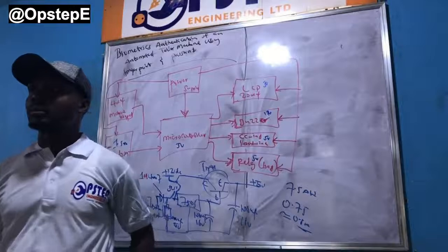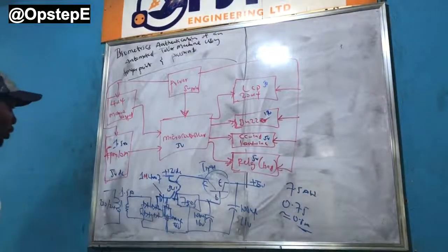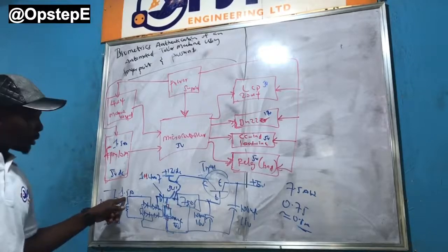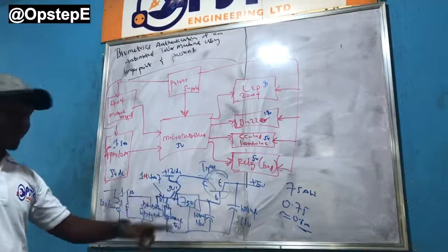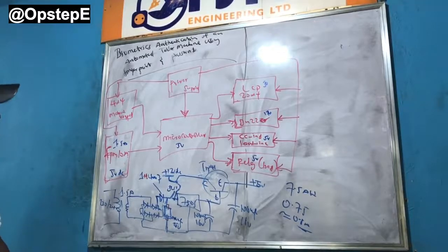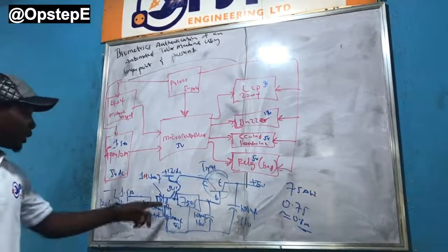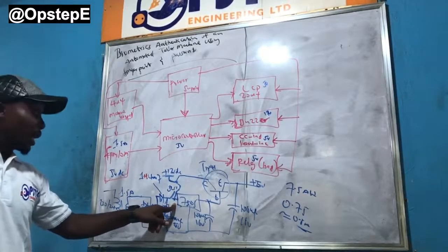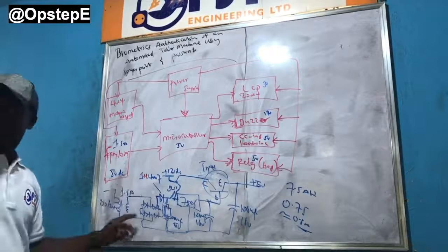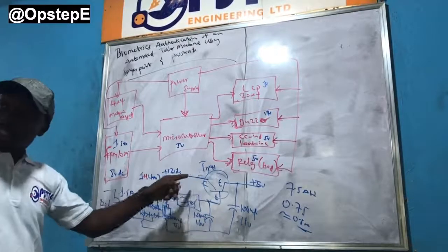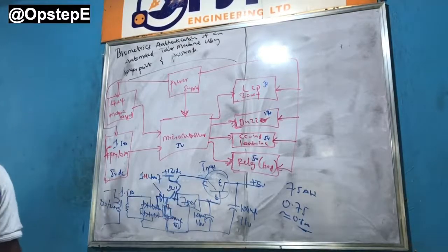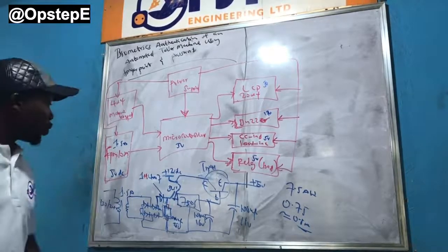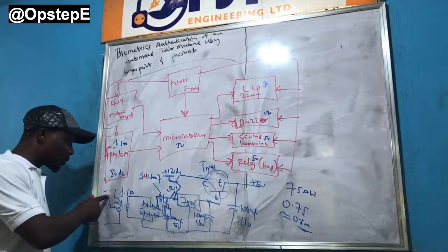Maybe you can just start from the main source and use a capacitor. You tap the AC from here, into this diode to rectify it. Okay, that's another point. But then the switch is here. What that means is that even when the switch is off, there's a signal going to the collector of that transistor. Only the collector. You've got a good circuit design unless you return the switch to this place.